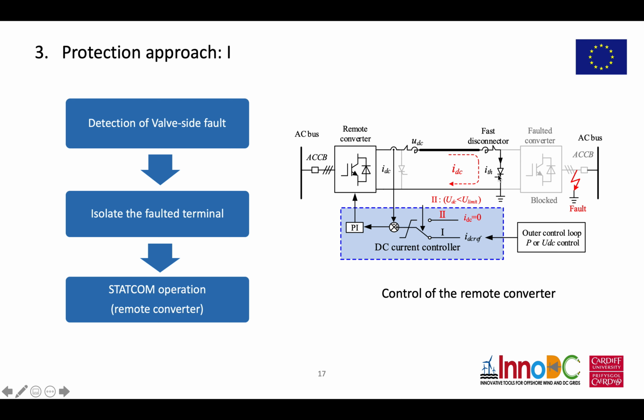If the Thyristor branch is triggered to protect the faulted converter, it will also cause another consequence, which is that it will cause a short circuit of the DC grid, which is also a fault for the whole DC grid. But a good direction is that the full bridge MMC converters can control the DC side current.